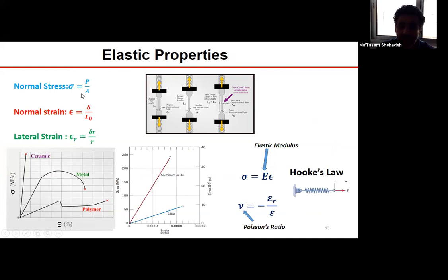So if we focus on the first type of loading, that's when we have a rod subjected to an axial load, and we look at the behavior by which the stress changes with the strain, that is the force versus the elongation, if you like, then the behavior in most materials will be initially linear elastic. It's similar to a linear spring, and therefore Hooke's law applies.